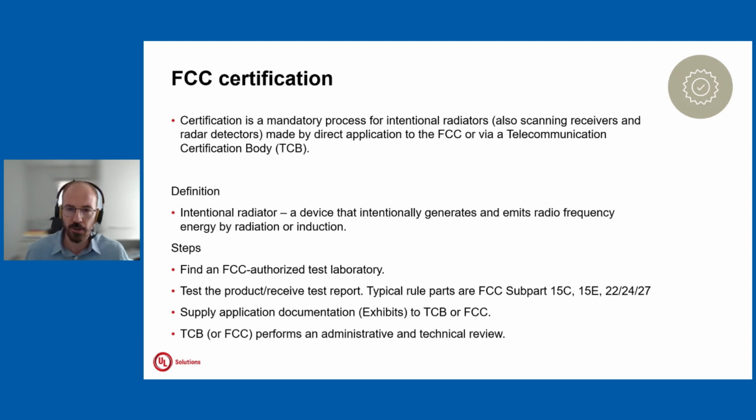Step number 1 is you need to perform testing against FCC rules. Depending on the standard, you will be considering FCC 15C or 15E. Maybe it's a Wi-Fi 5 gigahertz. You will need to have a look at which rule part you need to test against, in an authorized and accredited test laboratory like UL Solutions. Once the test report is obtained, then